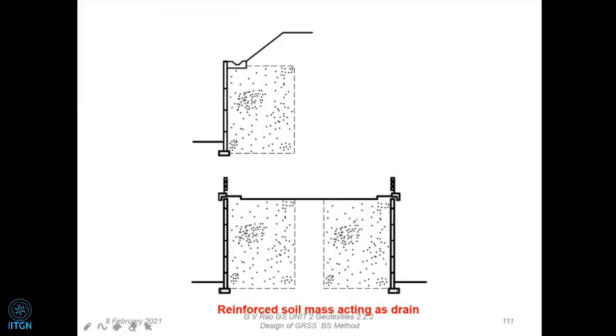So the importance of sandy soils or granular soils is that they are easy to construct, there is no pore water pressure build-up during construction, and of course it allows the drainage to take place such that there is no standing water left over anywhere. Nevertheless, we do provide some drainage measures as a precaution, particularly during construction. We provide some pipes and things like that. When we go into detailing, we'll also see those things.